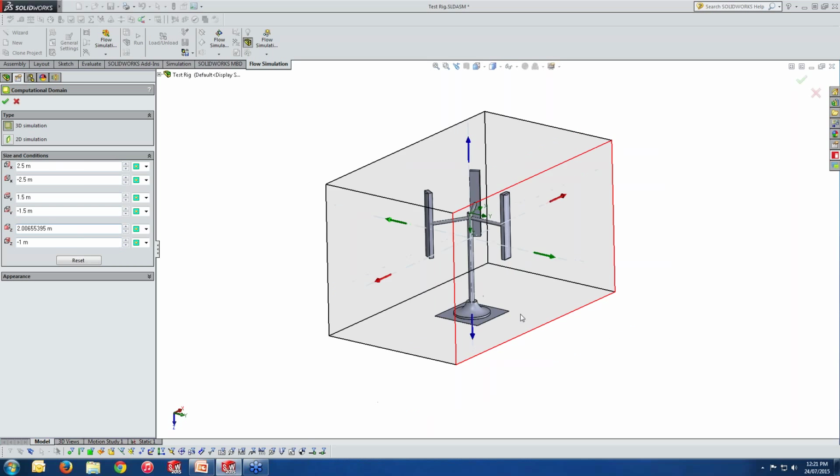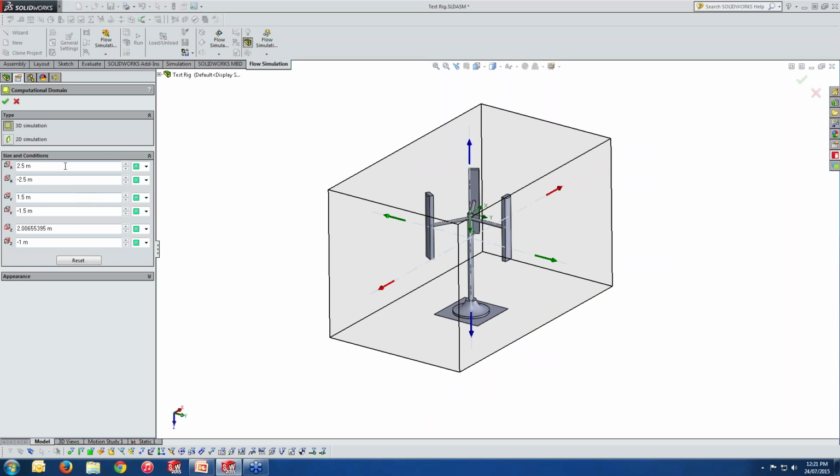One other good thing you can do in this case, in any of the XYZ directions, is say there is a symmetry, meaning exactly the same model is repeating in the X plus direction. That is very good since you might use a symmetry in your simulation and you would like to reduce the calculation time.